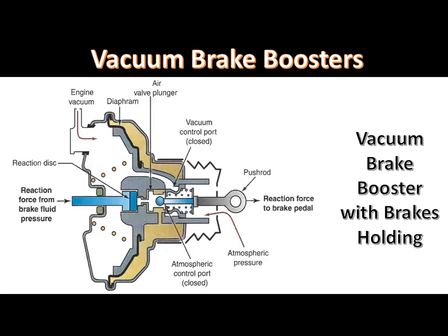When the brakes are being held at the desired stopping force, both valves are closed to trap vacuum and atmospheric pressure and keep the diaphragm in a hold position. A reaction disc between the booster diaphragm and the master cylinder pushrod provides brake pedal feel to the driver. This is the hold mode.